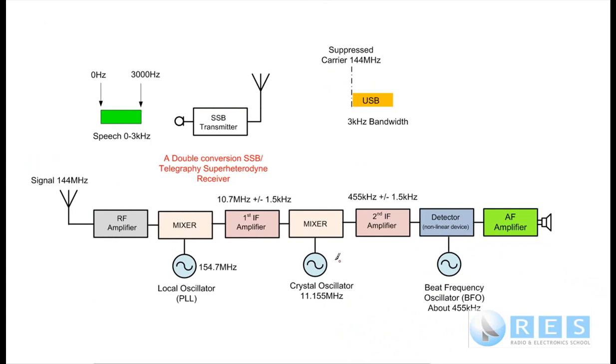There's another thing I want to talk about, and that's called automatic gain control. These receive amplifiers, these RF amplifiers, are very, very high gain and very, very sensitive. If a very strong signal is received, it's possible that the strength of that signal is so strong that it could drive either the RF amplifier or one of the IF amplifiers into becoming non-linear.